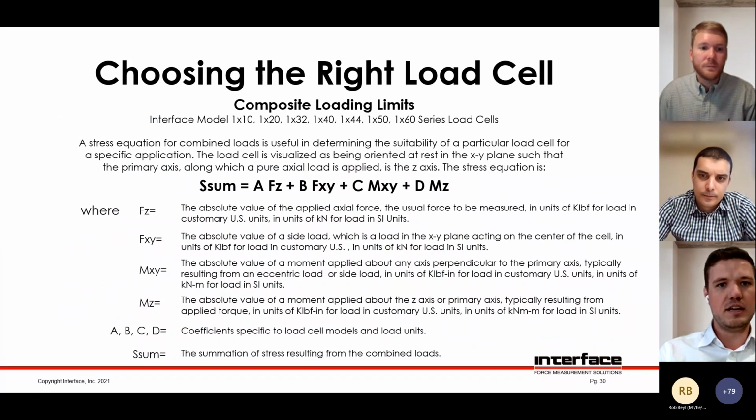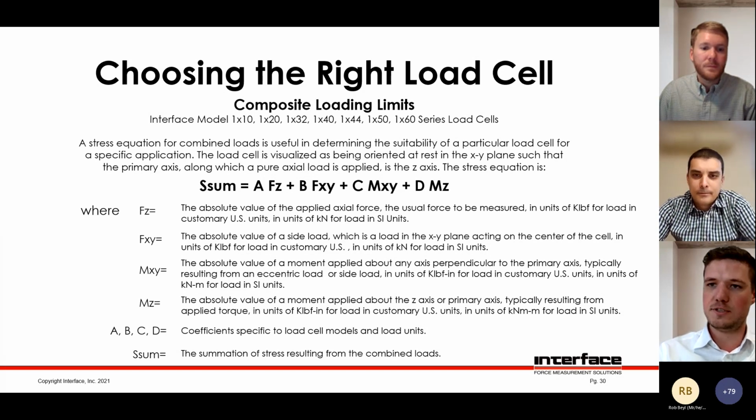Here you can see some of the calculations we can do for composite loading. So that's loading in the primary axis as well as off-axis loads or moments, torques. We won't go into too much detail here as this is load cell basics, but if you did need to discuss composite loading with your application engineer, they are equipped to talk about that. And as Jeff mentioned, to recommend an angle of mounting or a specific type of load cell that can best deal with the loading parameters in your application.